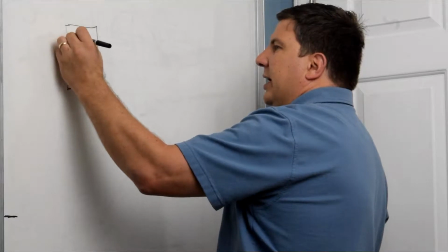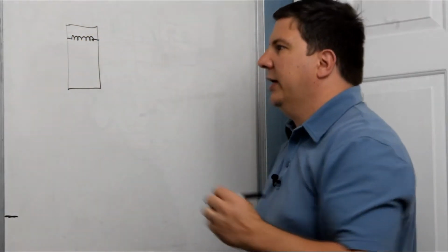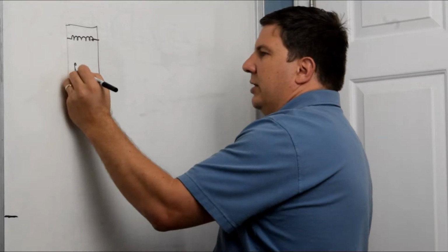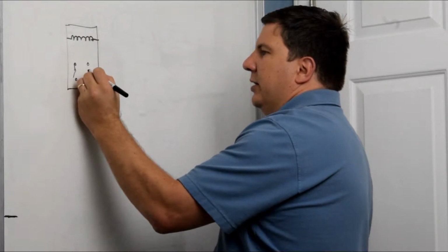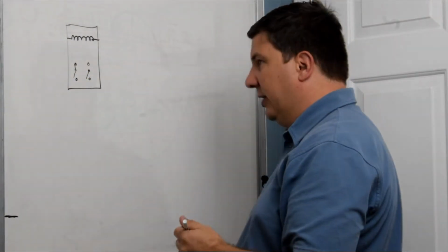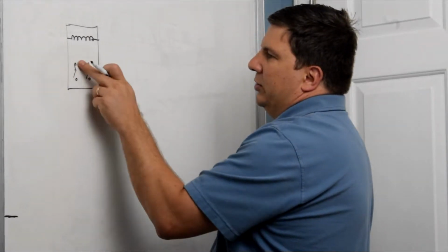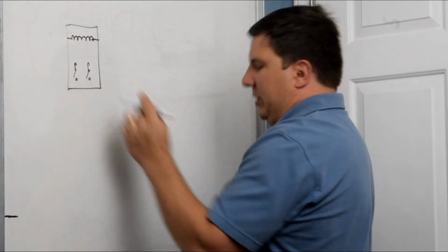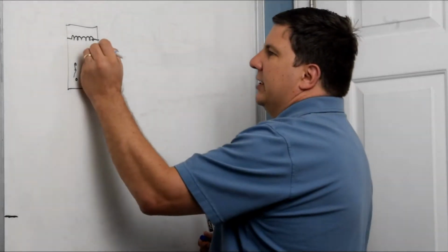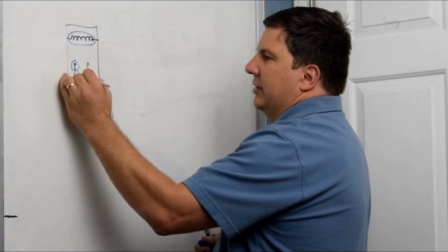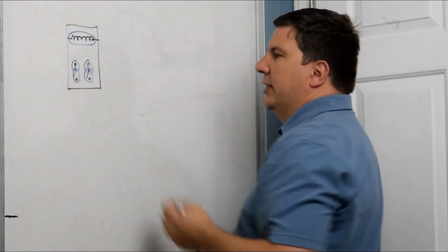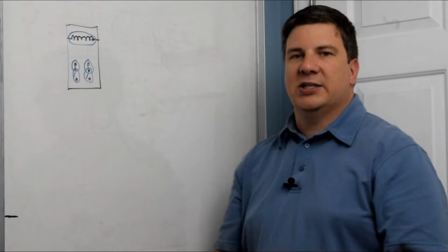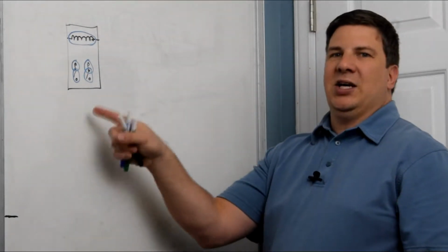All right, we have a relay here. It's got a coil. And then usually they have two sets of contacts, and those contacts can be normally closed and normally open. So what you end up having here is a normally closed set of contacts between those poles, and then when it energizes, you'll have a closed contact between those ones. So what you have is the coil, and the contacts, and you can see that's pretty complex. You can have relays with 4, 6, 8 contacts if you need it, so it gets quite complicated there.